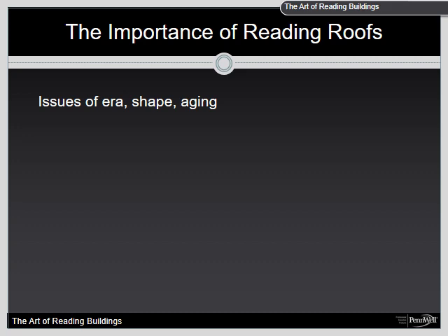The roof of a structure is normally 1/5 of the primary components of a building. And fireground operations are usually conducted below and/or above the roof. Knowing the type of roof and its potential structural integrity can directly affect fireground efficiency and safety.